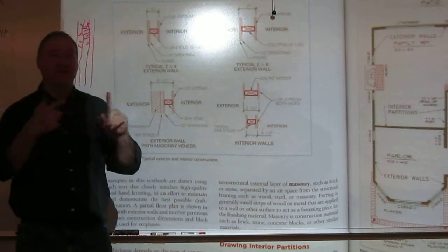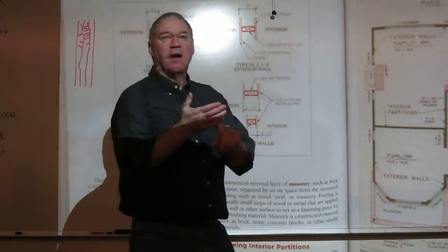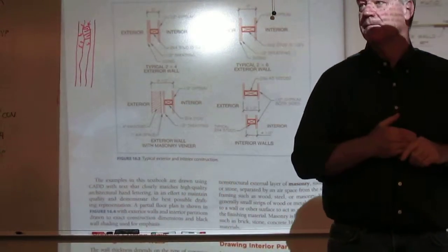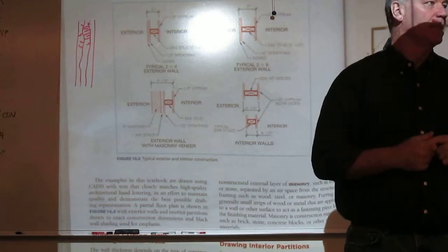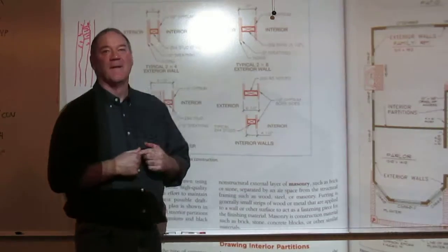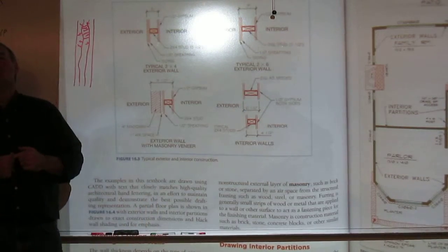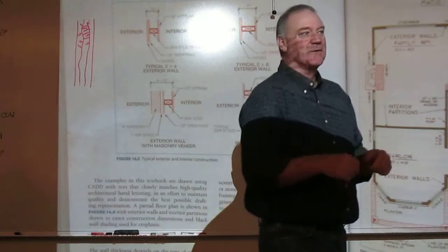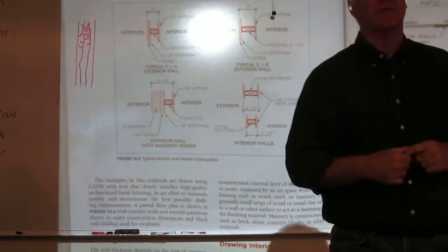Insulation, by the way, if it's an interior wall, we're really not worried about thermal insulation. Usually it's a sound barrier. So we're insulating it to kill sound. That would be the other reason. Cost? No, it's not. It's more expensive to go 2 by 6, because really you're buying material, so the 2 by 4 is cheaper.